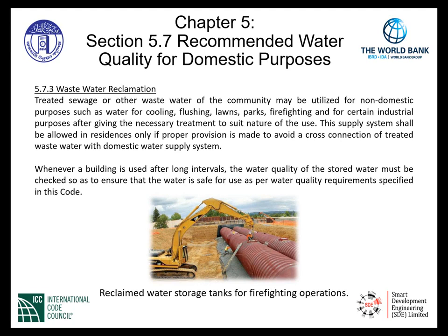In many cases, the water must be treated due to possible contaminants in the water. It must be filtered to remove certain particulate matter as well. This supply system shall be allowed in residences only if proper provision is made to avoid cross-connection of treated wastewater with domestic water supply system.